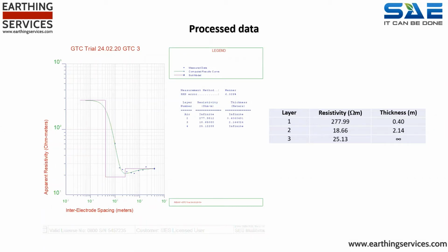To be clear, if an accurate soil resistivity survey has been undertaken, and as long as the installation is effectively completed, then an earthing system designed by CDEGS is likely to be within 0.1 of an ohm of the final system test.